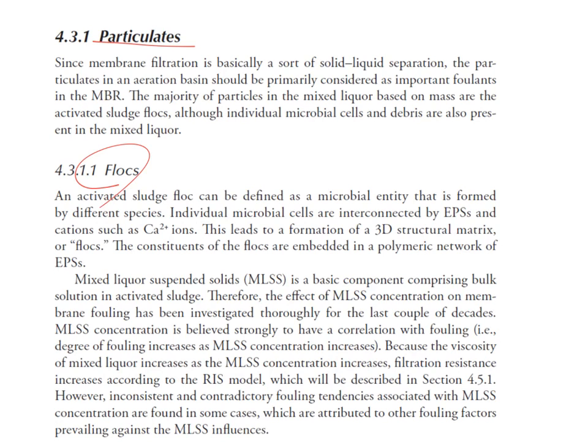The MLSS is a basic component comprising the bulk solution in the activated sludge. Therefore, the effect of MLSS concentration on membrane fouling is a very interesting topic. Sometimes we see that as we increase MLSS, the fouling is accelerated, but sometimes we see a very weak relationship between the MLSS and the fouling propensity.